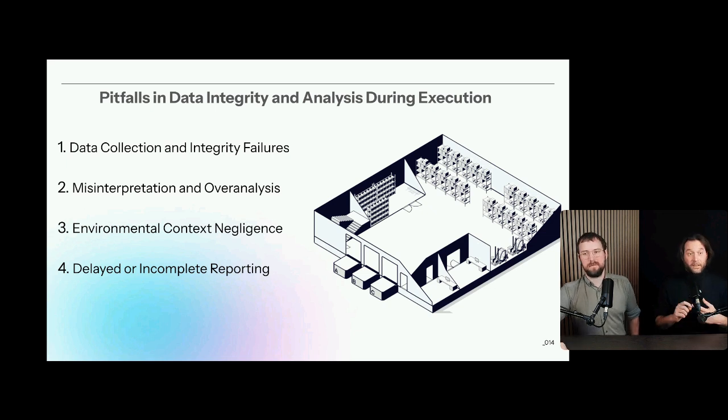Absolutely. So at the end of the day, it's about communication, making sure that the equipment is fit for purpose, like the monitoring equipment, and have your calibrations in place. This is also to prevent data corruption, because if a sensor is not calibrated, how do you prove that the measurements are accurate? And conduct periodic reviews to refine your methodologies, but also periodic reviews of your facilities and units, just to make sure they are in the same state as you assume they are.